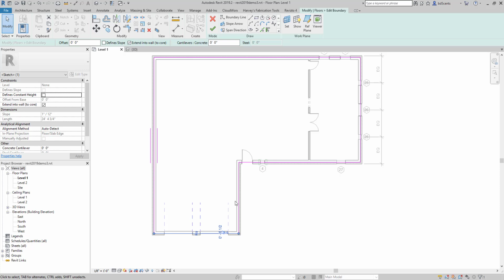The floor is not really close to being perfect. The garage floor would be lower than the house floor, and that's for water. The floor is 12 inches thick with no material assigned, and the edges of the floor are not correct. We will address all this later.